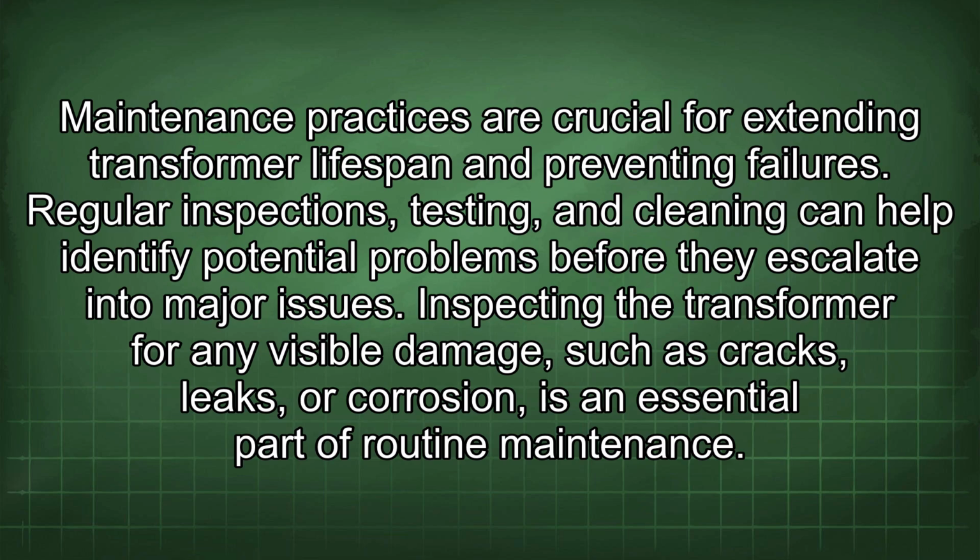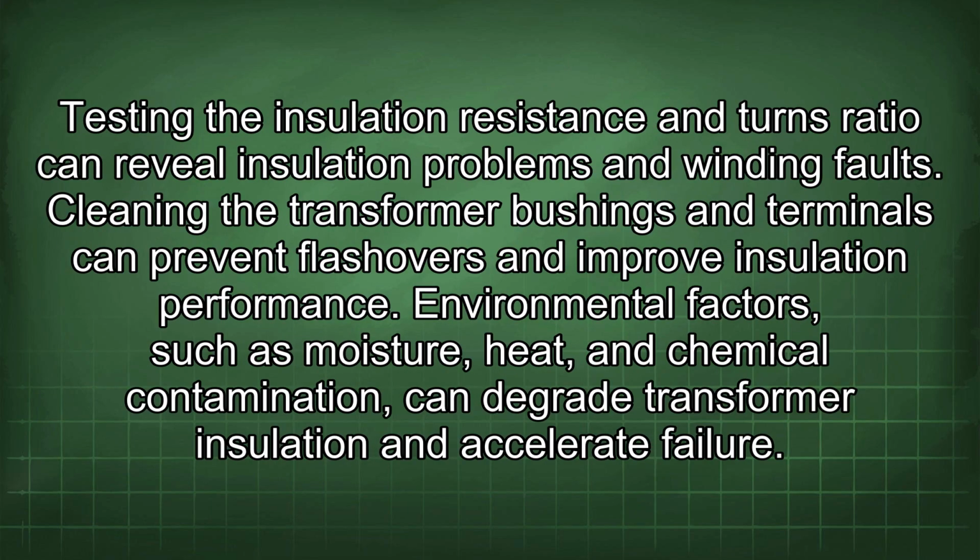Regular inspections, testing, and cleaning can help identify potential problems before they escalate into major issues. Inspecting the transformer for any visible damage, such as cracks, leaks, or corrosion, is an essential part of routine maintenance. Testing the insulation resistance and turns ratio can reveal insulation problems and winding faults. Cleaning the transformer bushings and terminals can prevent flashovers and improve insulation performance.